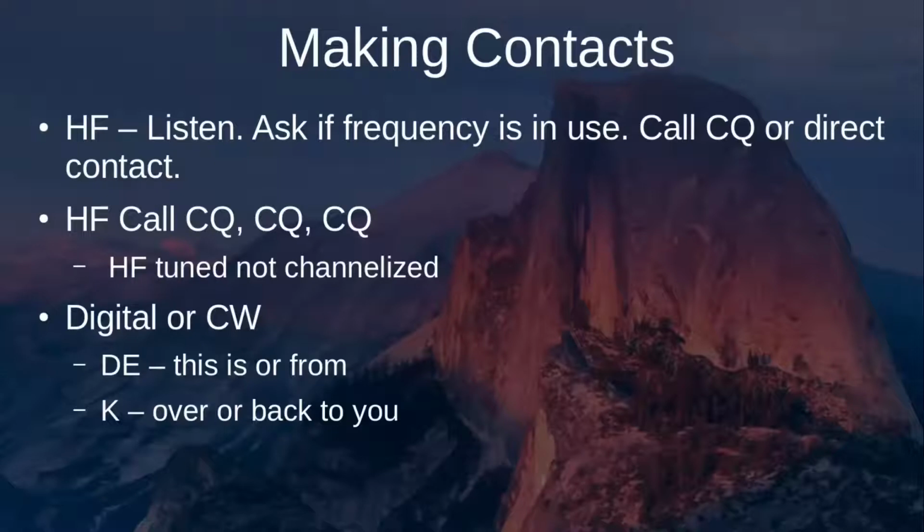So I wouldn't just call CQ, this is November 9 Whiskey India Bravo calling CQ, and then stop for a 5-minute time frame. They need time to actually see your transmission on that waterfall, or hear your transmission when they're scanning from the low end of the band to the high end of the band by just rotating the VFO dial, the tuning dial.